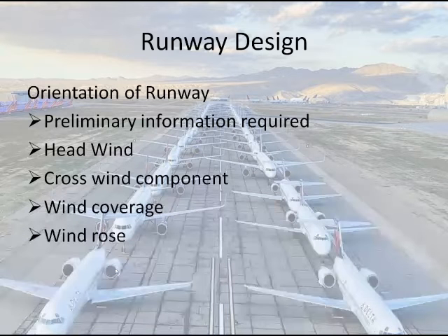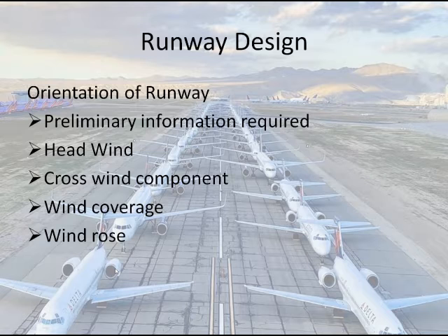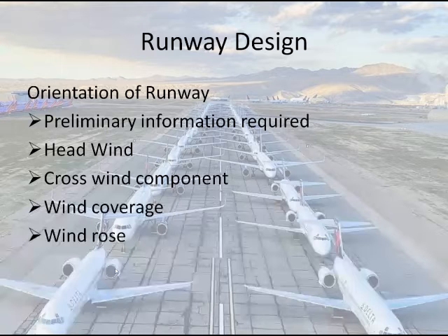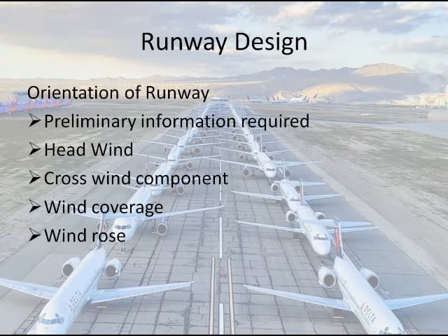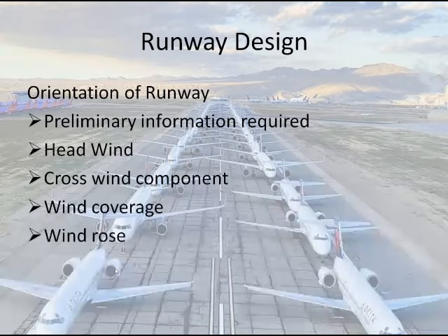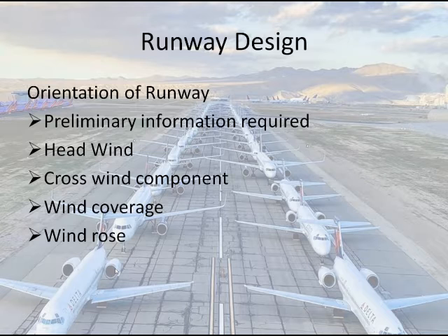The number of runways will depend on the volume of air traffic, while its orientation will depend on the direction of the wind and sometimes on the extent area available for the airport development. This is how the runway design is decided.